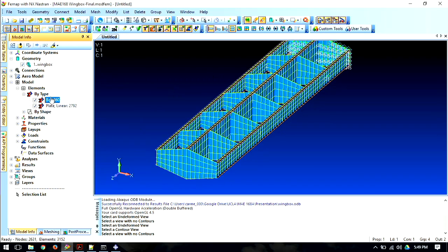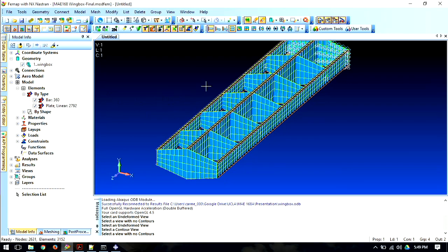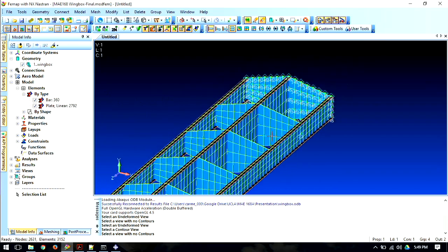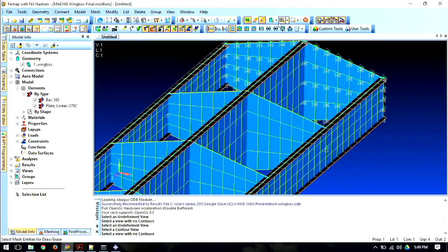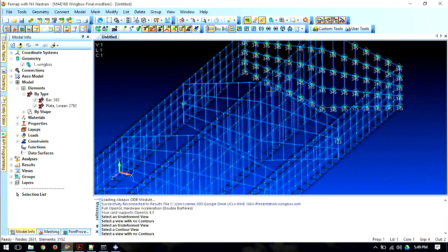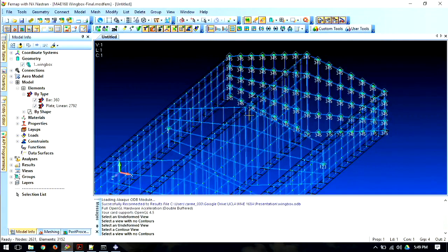And so that's what you see here. I have some bar elements, which are the beam elements. They call them bar. And the plates, you can see they're linear elements, and there's a lot of them. And they're all connected here. Out here you can see 3, 4, 5. This is the symmetry constraint. 3 goes with the x direction, 4 is the rotation about the x, and 5 is the rotation about the y. So in this plane of symmetry, that's where you would constrain the out-of-plane direction, and you would constrain the out-of-plane moments.